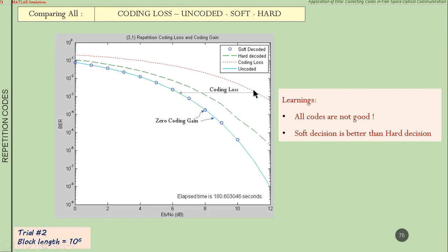during transmission and reception. And then after decoding, the repetition code could make up only for the coding loss it created due to the addition of redundancy, so it is not useful. We are not improving upon the theoretical uncoded message that we are sending. We have not achieved a better bit error rate at a given SNR. We have not created a less SNR signal.